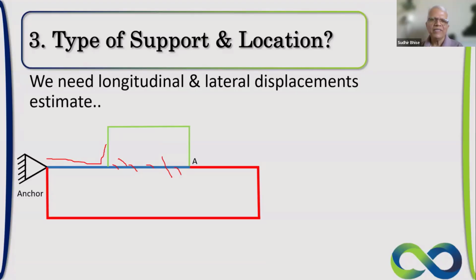Why is blue going to be higher than green, or why is red going to be very low? How is the expansion defined? For example, at point A, I want to find the expansion. What do I do? Length multiplied by the expansion coefficient, alpha times the length, will give me the expansion.